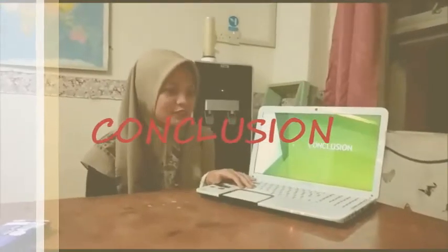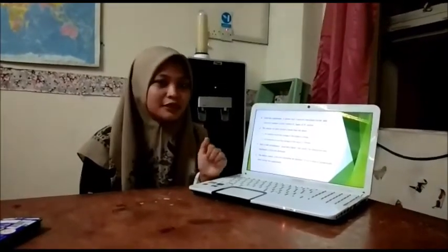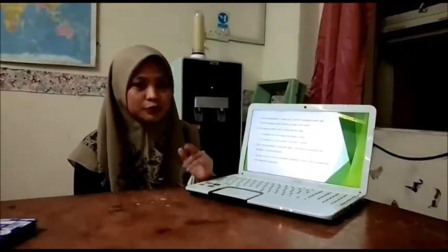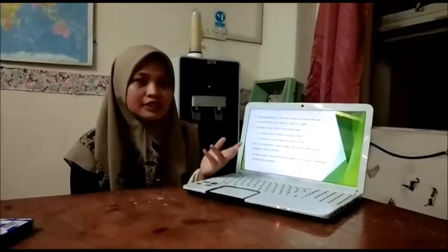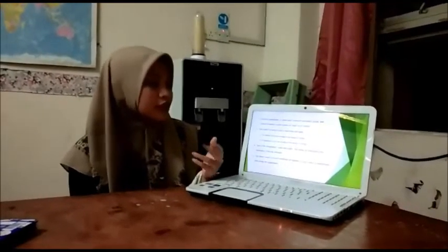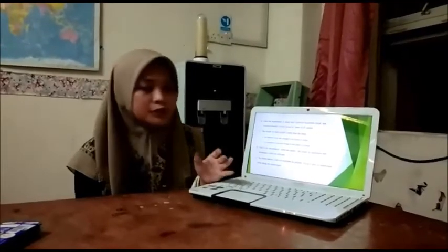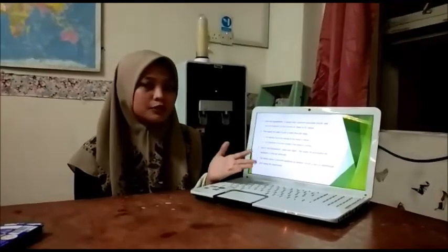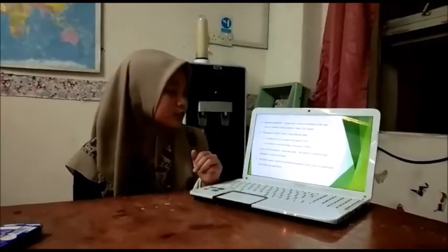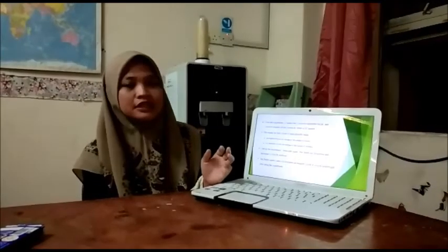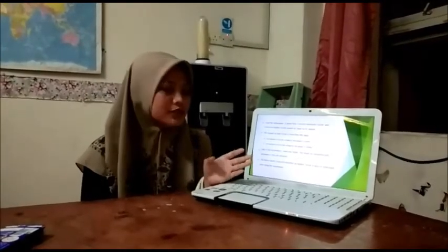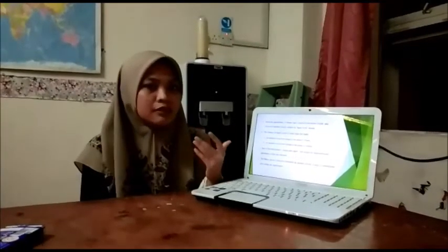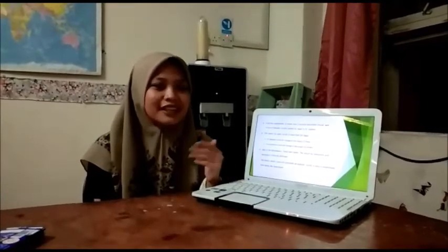In conclusion, the experiment shows that the Cockcroft multiplier circuit and the Cockcroft doubler circuit convert AC input to DC output. The output for both circuits is more than the input voltage. For the doubler circuit, the output voltage is 2 Vmax, and for the multiplier circuit, the output voltage is 2n Vmax. Due to disturbance, noise and ripples, the simulation and hardware results are relatively different. From the experiment, we understand more about the Cockcroft multiplier circuit and the Cockcroft doubler circuit.